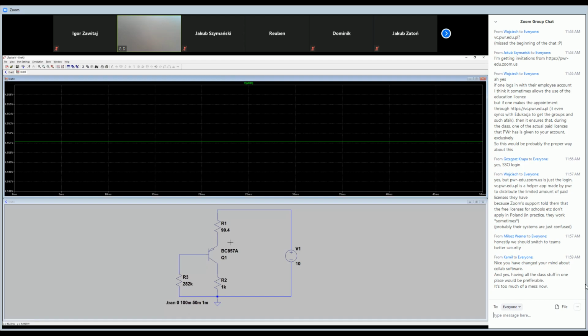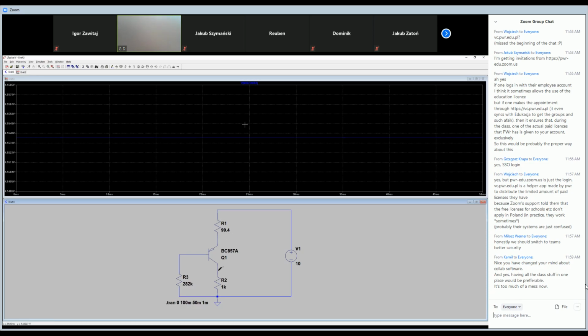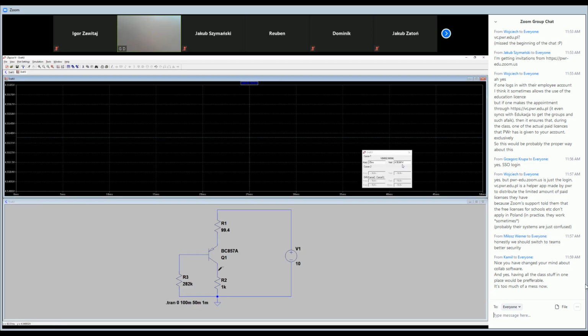Okay. What is the voltage drop between collector and emitter? We set it as 4.5 volts. However, as you see, I have to use the reference probe here. Okay, I've got it. How many is it? Oh, it is 4.55 volts.